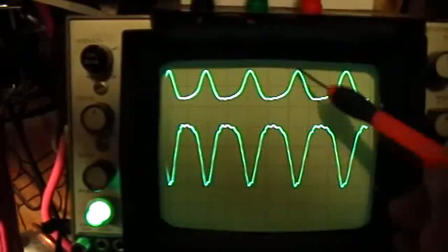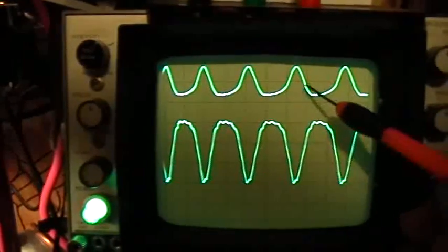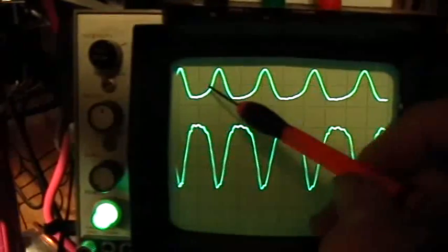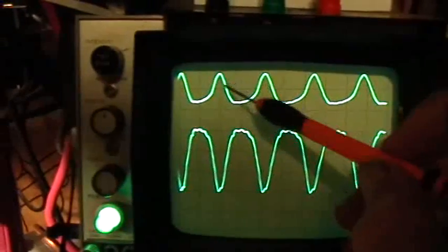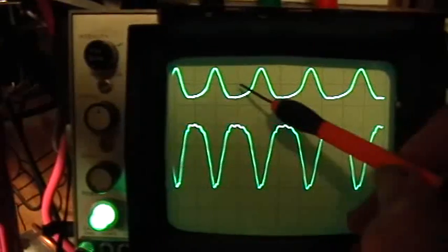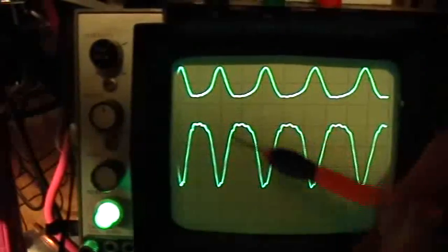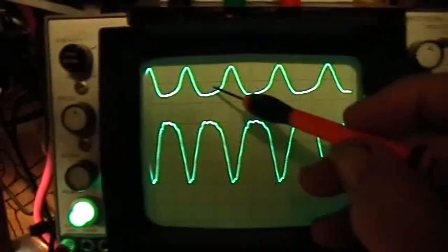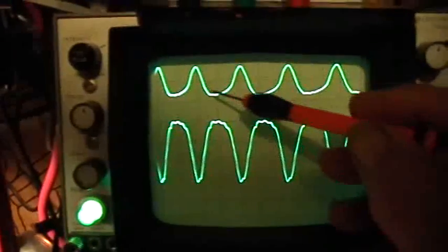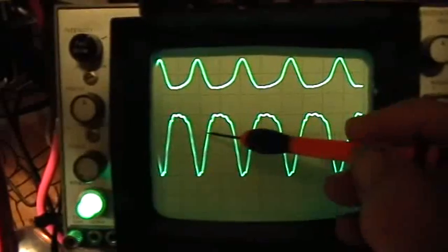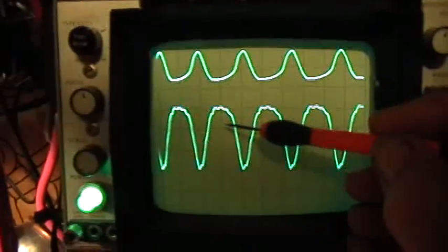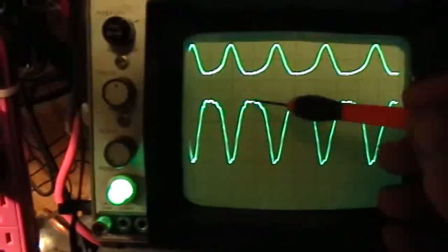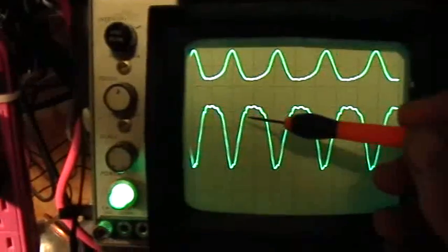Because remember this is oscillating around the battery voltage, which is this graticule marker or just below it right here at 50 volts, right? So you've got an area above that 50 volts and an area below that 50 volts. Since the sum of the integrals is equal to the integral of the sums, you can take this area and multiply it by this area, and effectively that's the same as doing the multiplication first and then integrating, okay?